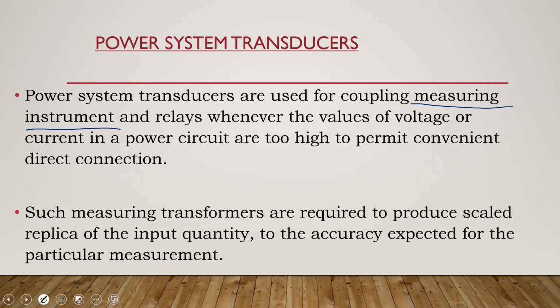The standard output, for example, for your VT, your voltage transformer, and by the way, just to make the distinction here, a quick comment regarding VTs. If you have an older textbook, you might see it referred to as PTs, potential transformers. Same thing, but in the modern world, we call it VT. Your voltage transformers, the standard output is 110 volts phase to phase, all right? It's 110 volts.